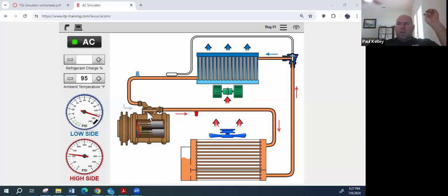You could also, if you guys were picking up on what we were doing during that diagnosis together, feel and test to see if that relay's clicking. If the relay's clicking, that means the control side of the circuit is working. If the relay is not clicking, that means something is not activating the relay. So you could go in two directions. If the relay is clicking, then you're really going to have to check for voltage at the compressor. Totally agree. If the relay doesn't click, however, then you may have to start looking into other things, right?